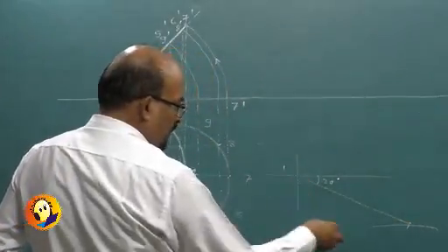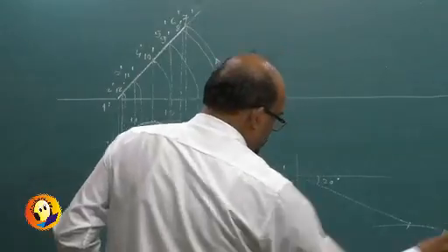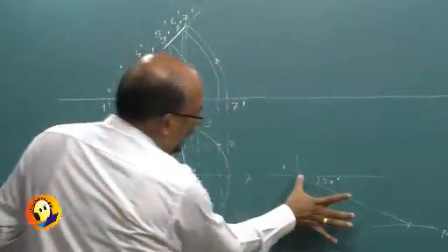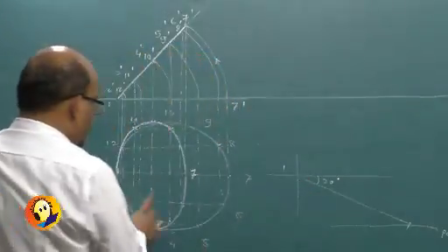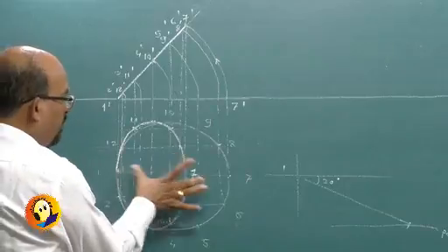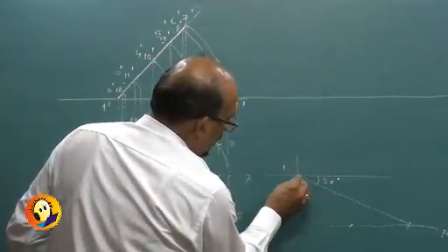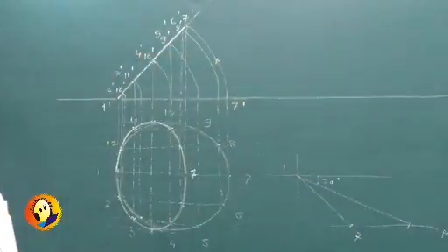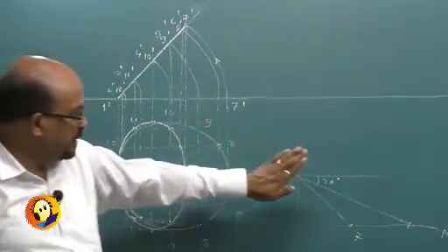So this is 0.1. I get path of 7, and then take the apparent length that we have got and cut the arc. So we will get the angle made by the plan with XY, and this becomes 17. So all this entire lamina is to be lifted, this ellipse, and to be drawn here.